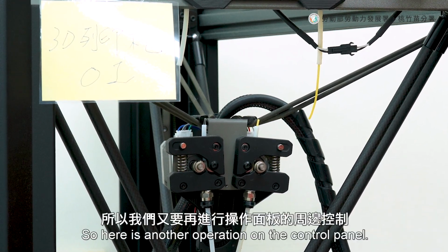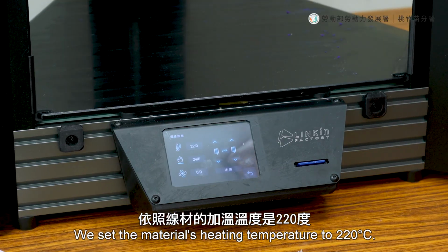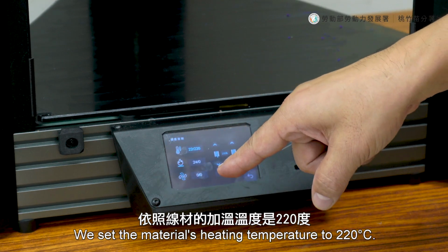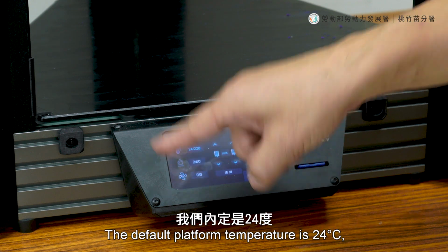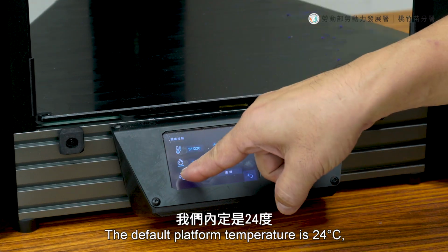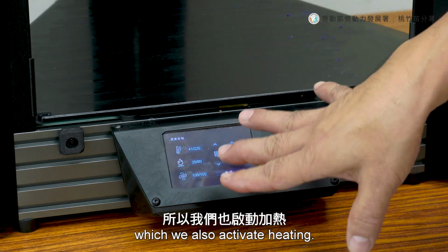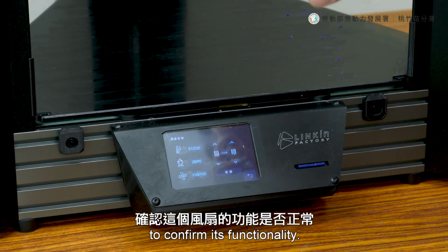So here's another operation on the control panel. We set the material's heating temperature to 220 degrees Celsius. Activate heating. The default platform temperature is 24 degrees Celsius, which will also activate heating. The fan also needs to be turned on to confirm its functionality.